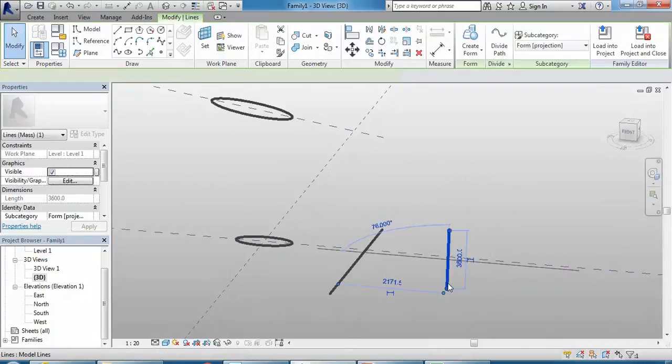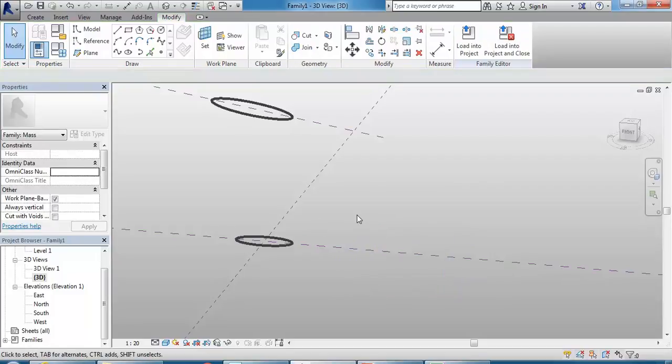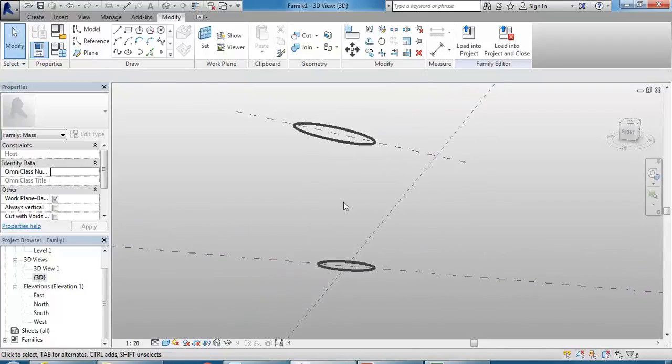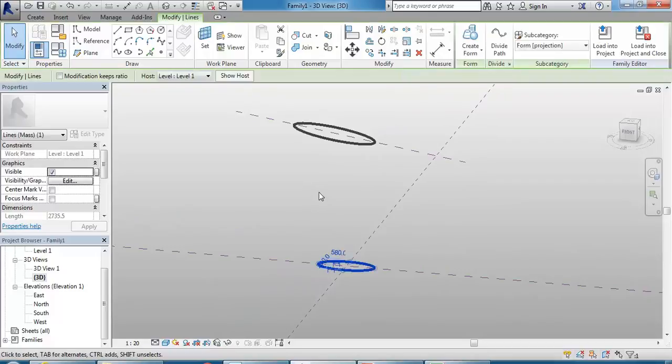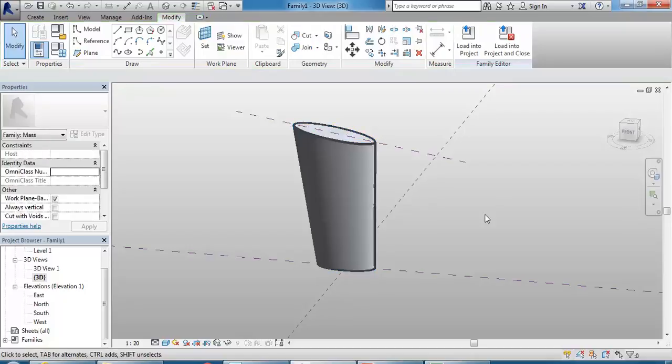So I think in some ways they tried to be a bit too clever by half when they came up with this modelling system, because essentially you can get all of the modelling operations, extrusion, blend, revolve, swept blend, just by selecting different combinations of shapes. And you can actually do a lot more than you can do with those modelling tools, but you need to kind of know in advance what shapes you need to get to those different final outcomes. But once you've experimented with it a little bit, you'll see it's fairly straightforward. If I select these two shapes, Create Form, it knows to do a blend.